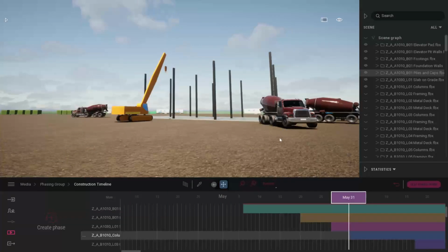When it was done, it showed as a completed element like we're seeing on my screen here. I could have set that up in Twinmotion by duplicating all of the assets so there were two versions of each, overriding the materials for one of the copies, and triggering it 5 days prior to it being finished. So you could get that same look.